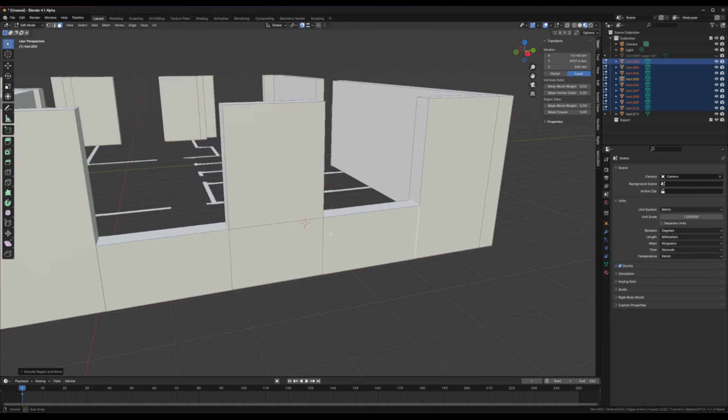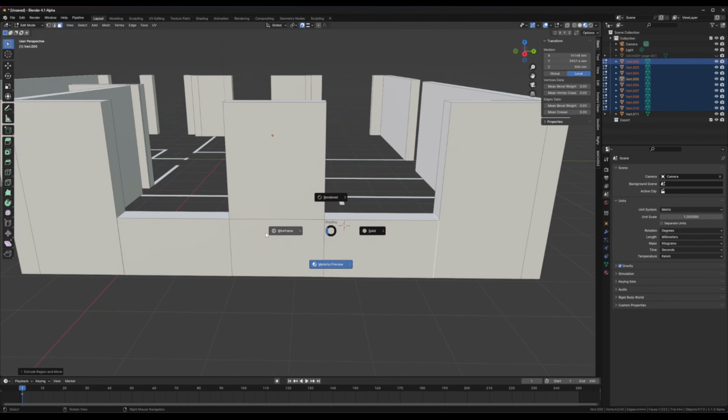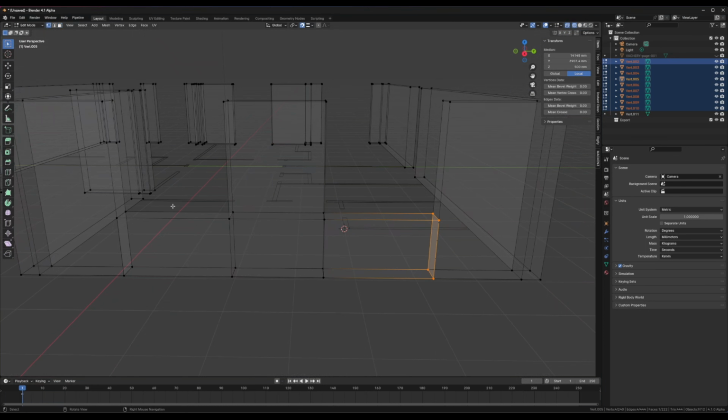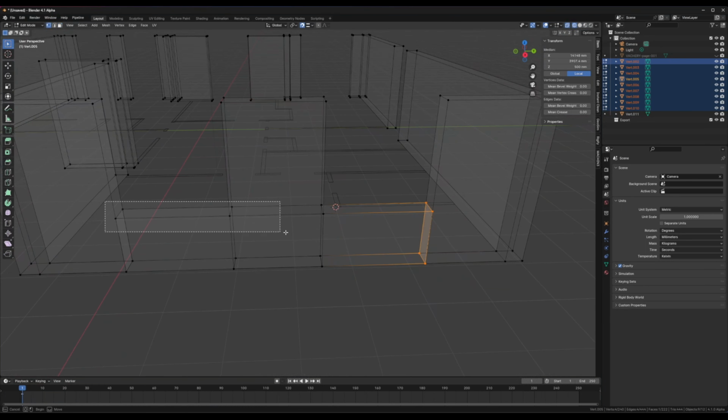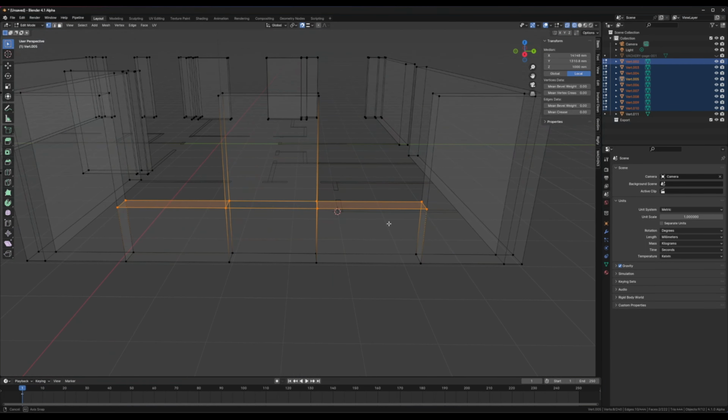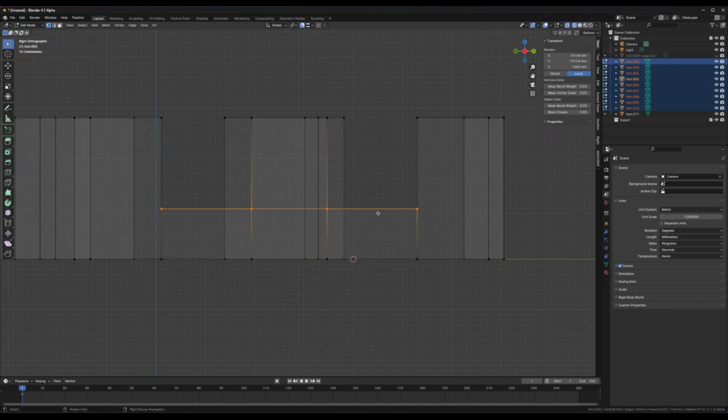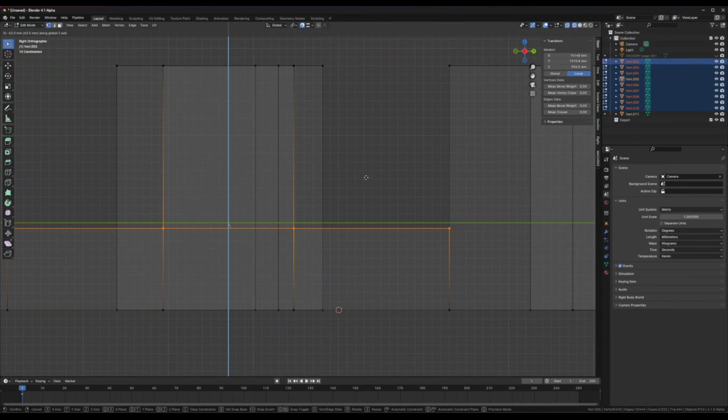And if you wanted to move them all down, well, it'd be pretty easy to do that. We could just come into wireframe, come into vertex mode, select the verts here, and we could, let's say, move them down. So we could snap it to this view, G, lock it to the axis down, and then let's say move it down 100 mils. So like move it down to 900 mils total instead of 1,000.